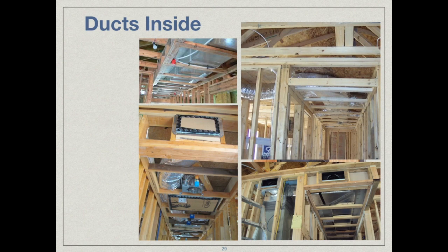The key to success with doing Ducts Inside is to design it into the building. Designing it into the building means that your designer has to place the registers, has to place the ductwork and all the connections between there. And they also have to consult the heating contractor to make sure those ideas will work. So you really have to bring the heating contractor in early on in the design phase. You can't just throw up the shell, have the guy roll up in his truck and expect the heating contractor to get all the ducts inside. It has to be planned in advance. The website that I mentioned is a really great way to get smart about how to make that happen.